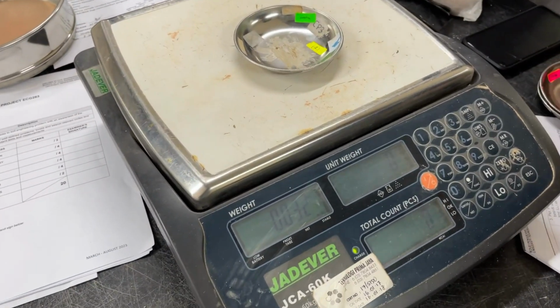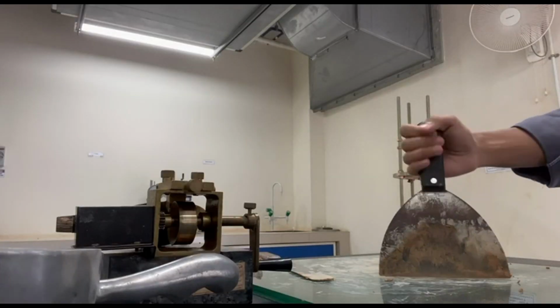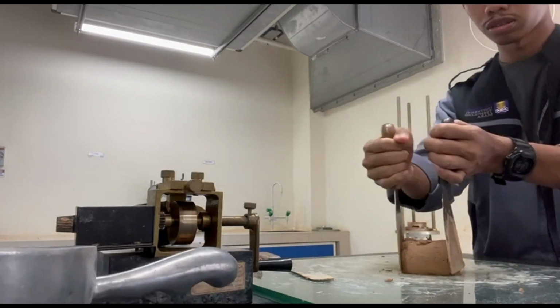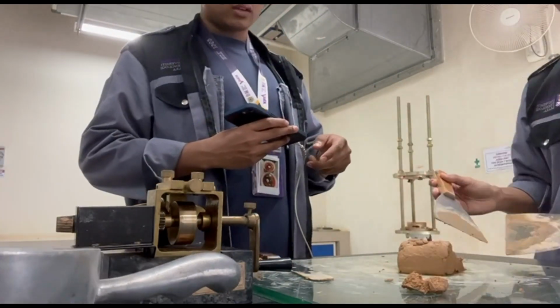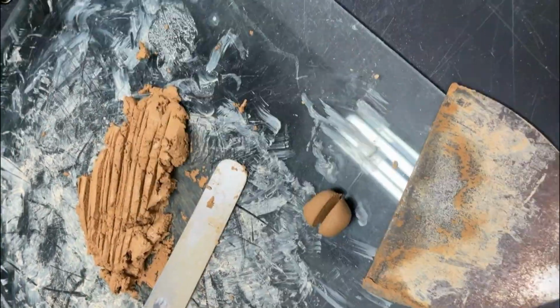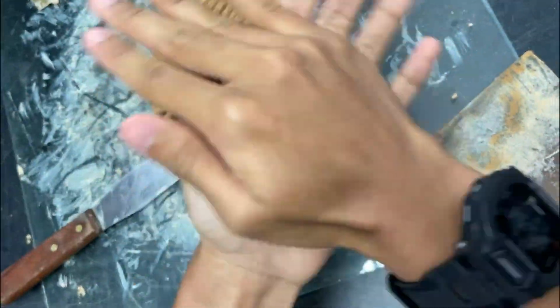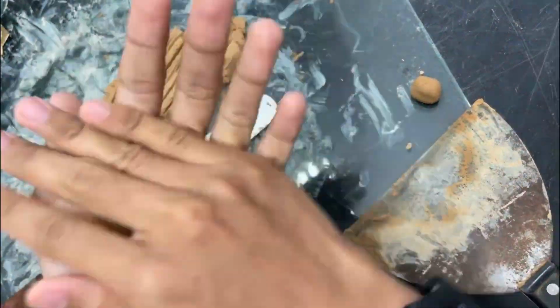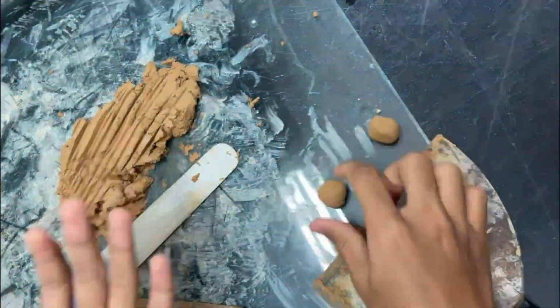Plastic limit test. An empty moisture can was weighed and recorded on a datasheet. 20 grams of the original soil sample that have been separated was taken. The soil was rolled to form a ball shape and cut into 2 pieces. Then, each piece was formed into a ball and cut into another 4 pieces.